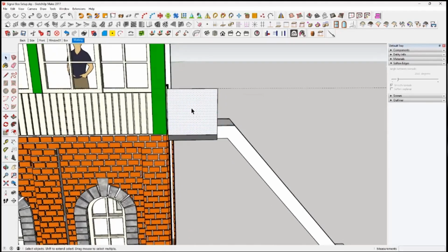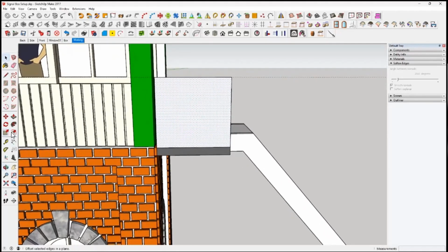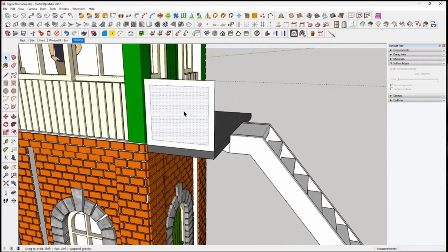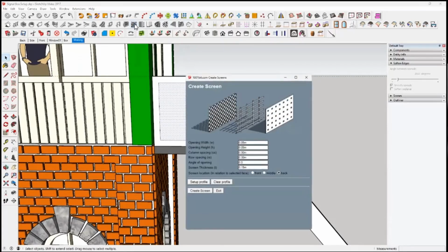On the end panel, we want to make something fancy in the middle. We'll offset that one. Bring it in 0.1, 1 mil, sounds about right, that'll print. And this panel here, we can make decorative. So if we go up to our 1001 bit, there's a plug-in called Create Grills Gratings.